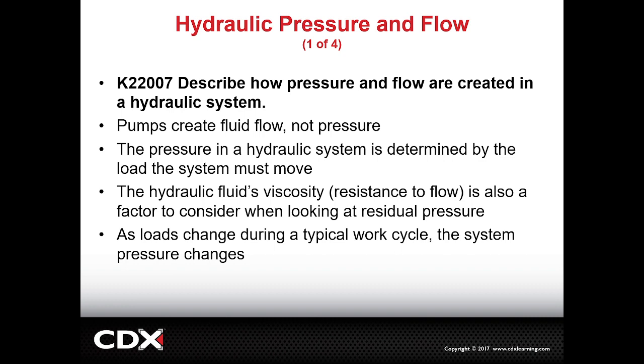Pressure in a hydraulic system is determined by resistance to flow, the load, what it is you're trying to do. The components, valves, viscosity, and so on all contribute to resistance, but are not that significant. Primarily, it's the load. As flow continues, pressure builds until the resistance is overcome and we're able to lift, dig, tow, or whatever it is we're wanting to do.